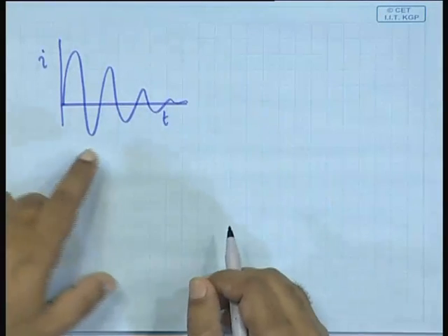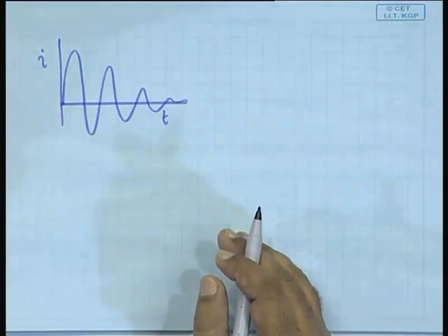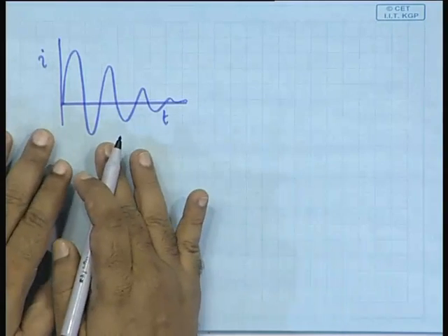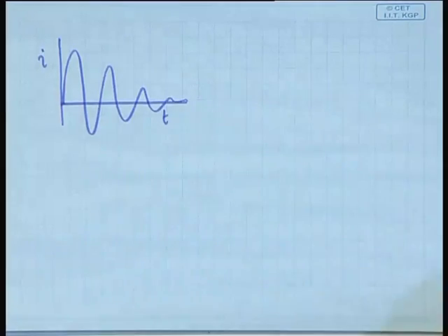In this case also, you cannot define the time constant in the same way, but there is an exponential term. So, instead of time constant, we can say that there are certain characteristic times in the system. One characteristic time relates to the time constant as obtained from the exponential. Another characteristic time relates to the period of the sinusoid. So, in this system, therefore, there are 2 characteristic times. So, instead of time constants, we will try to think in terms of characteristic times.